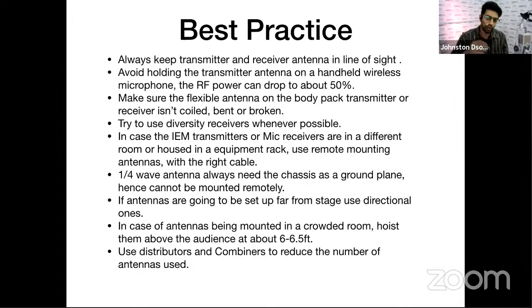Okay, so if you're putting your transmitter receivers in a housing, in some sort of a flight case, you make sure that you're using remotely mountable antennas. Now I showed you the 1/4 wavelength antenna, the small antennas.